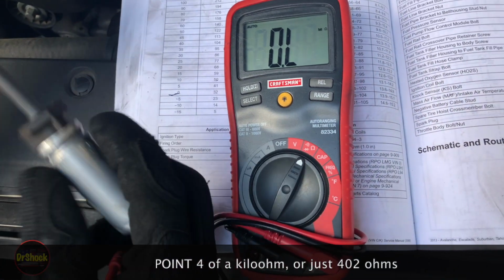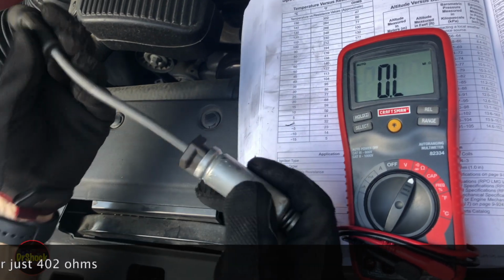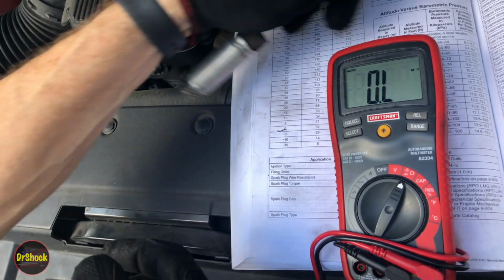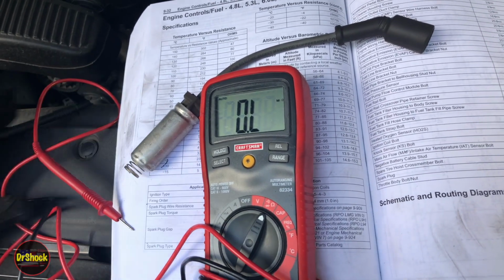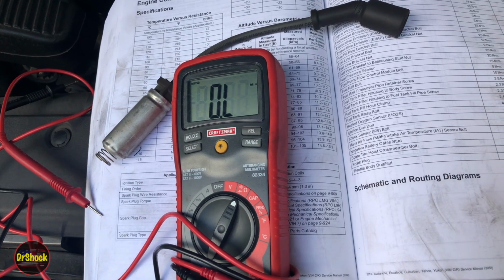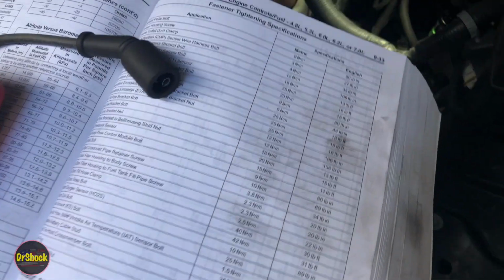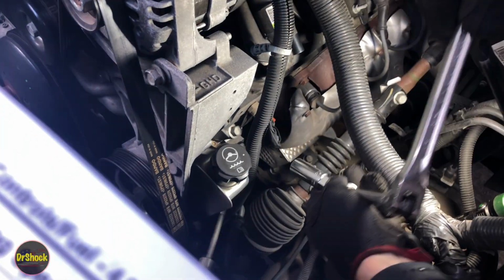Now, is that the problem? No. That's a problem, but that is not the problem. These are probably at the point where they're in need of being replaced. But it's not an open, so that's not causing our misfire, in my opinion. It's something we need to go service, but it's not the problem we're after. Let's go after the plug next.